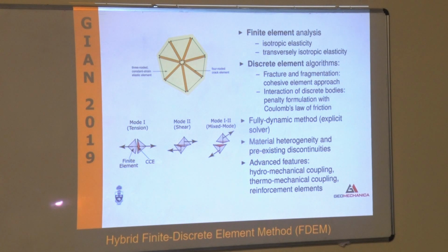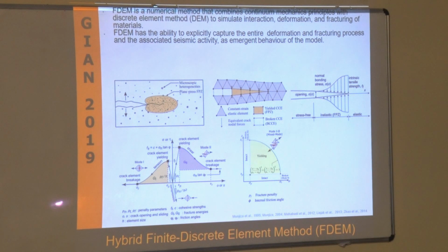And this coupling is fully coupled, meaning that when you change the stress, that stress has an influence both on the mechanical and the fluid part. What does it mean? If you have a fracture, you pressurize the fracture, that fluid will tend to open your system, your fractures. That means that you will apply a pressure to the surface of your crack. It will open, but because it opens, it will increase the volume within the fracture. That means the pressure of your fluid will decrease. So that means that it's fully coupled from one to the other. Okay? So that is really what we are going to use, and we're going to see a little bit more on the results. Before getting there, how this system is going to work.